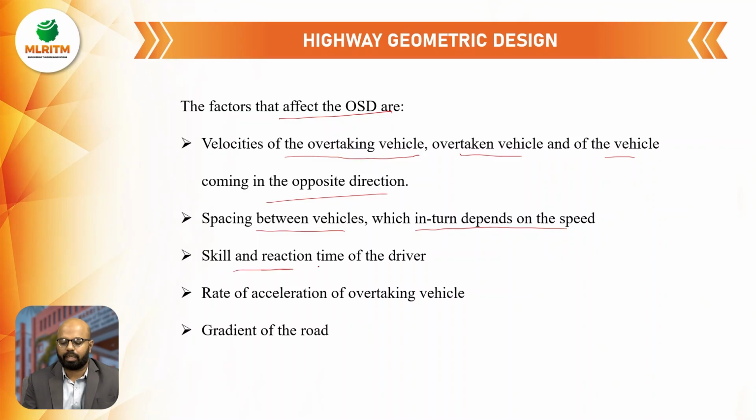Next is the skill and reaction time of the driver, which is very important. Reaction time comes here also, and the rate of acceleration of the overtaking vehicle. Next is the gradient of the road. These are all the factors that influence the overtaking sight distance.